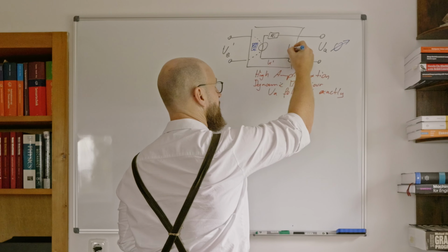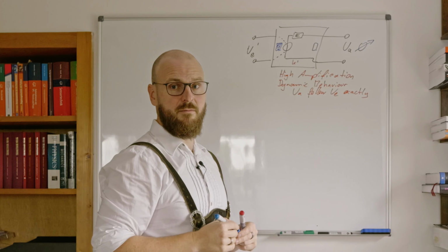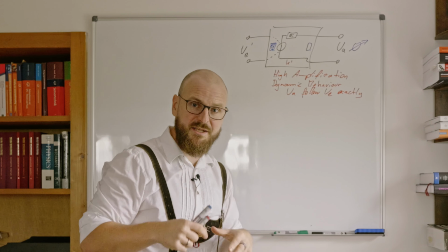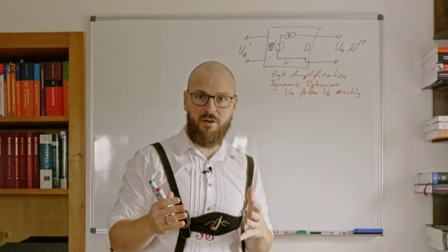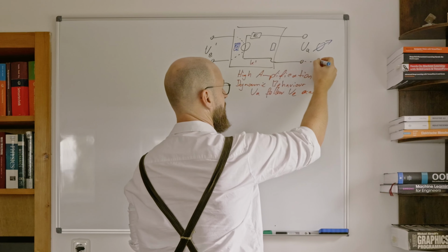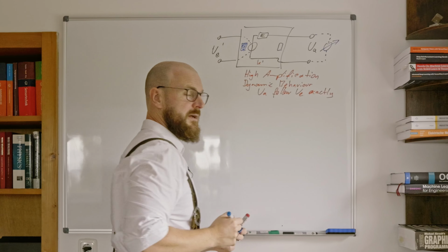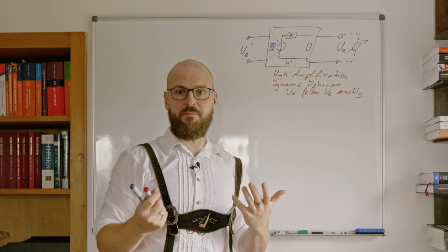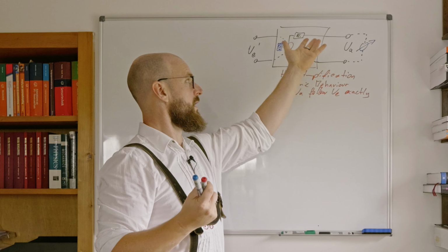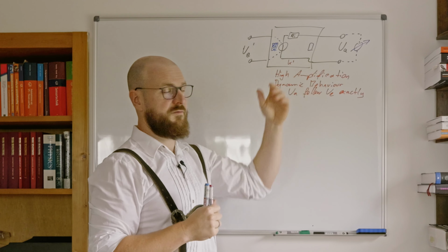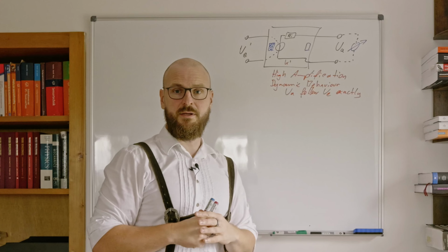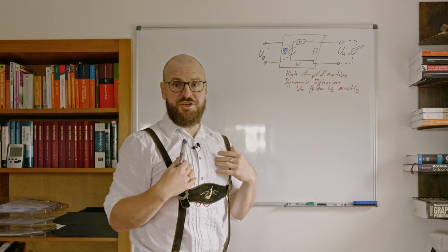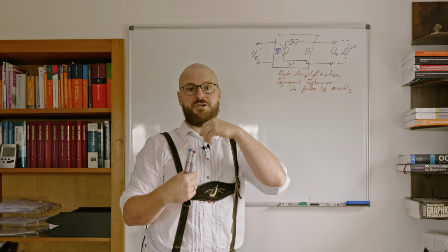So, speaking about electrical values, that output resistance should be very small, so that we can connect any voltage meter to the output and measure exactly the output voltage and nothing else, with no additional systematic errors which could result because of the internal resistance of the output side of our measurement amplifier. Yeah, that's the wish. That's what we want to have from such a measurement amplifier.